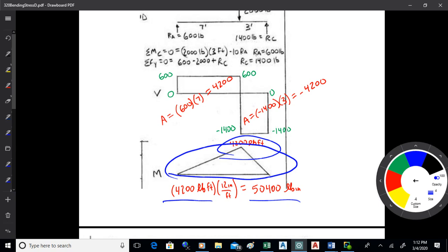You with me there? So if I'm going to make 10,000 of these and I'm just going to kick these beams out, I might take the time to custom design a beam and make the shape fit that diagram that I'm getting. But if you're doing a building, it's just not worth the design time and the fabrication time to do that. So if you do a building, which is a one-off, you design it once, and you're putting lots of time into the design work, you're probably just going to take that maximum value, pick a beam out of a catalog that'll work for that entire length at that maximum value, and put the thing in, and then get on to the next beam.